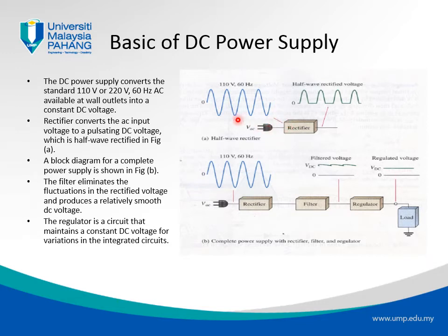When we are in a positive part of the waveform, if the diode is in forward bias configuration, it will continue to conduct the signal, and the output will look just like the input. As the signal goes into the negative part of the waveform, the diode opposes the direction of the current and cuts it off, not allowing the current to circulate in the opposite direction. So at the end, in a simple rectifier, we only have the pulse on the positive side.